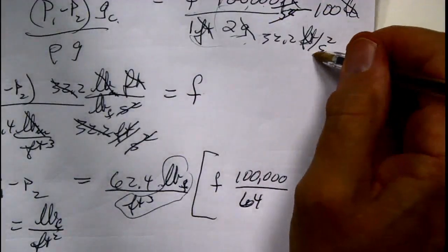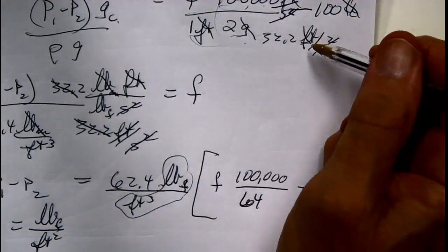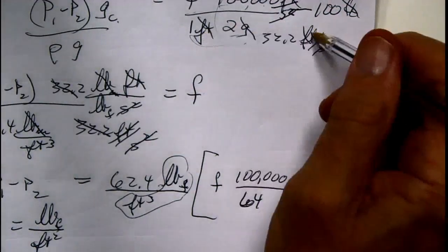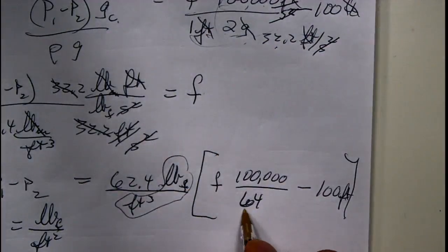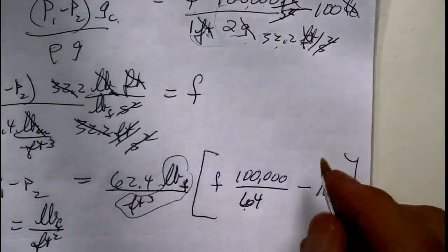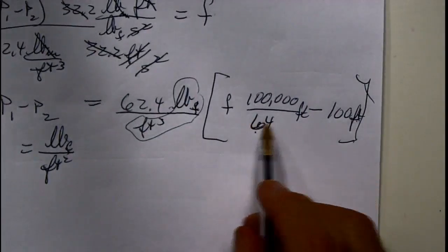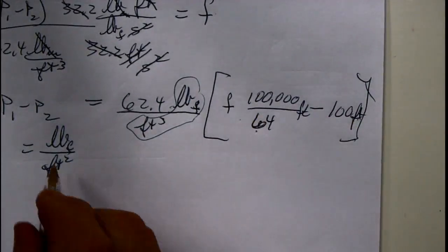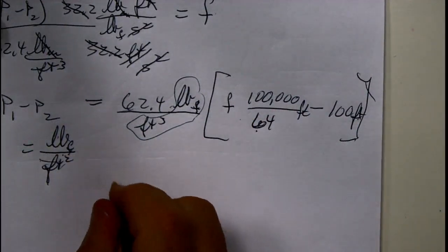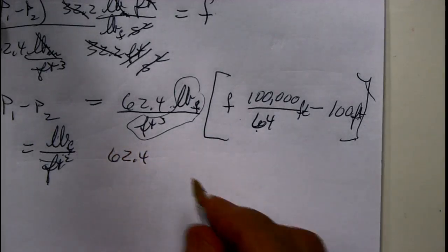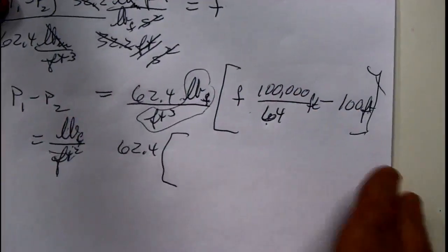So the second squared cancels second squared. Cubic foot divided by foot squared sitting here gives me a foot. 2 times 32 is about 64. And the units left in this thing will be foot. Okay. So I'm correcting my units. If I multiply through, I get foot pounds force per square foot. Now then, I got this 62.4, and now I have the number part. See, you separate the units out and work the number part.